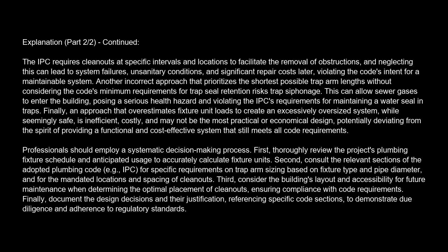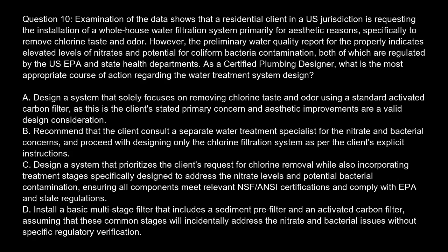Third, consider the building's layout and accessibility for future maintenance when determining the optimal placement of cleanouts, ensuring compliance with code requirements. Finally, document the design decisions and their justification, referencing specific code sections, to demonstrate due diligence and adherence to regulatory standards. Question 10.